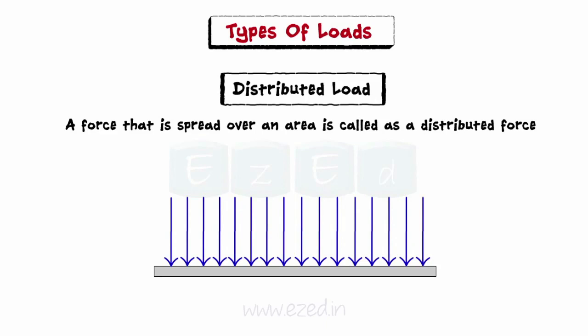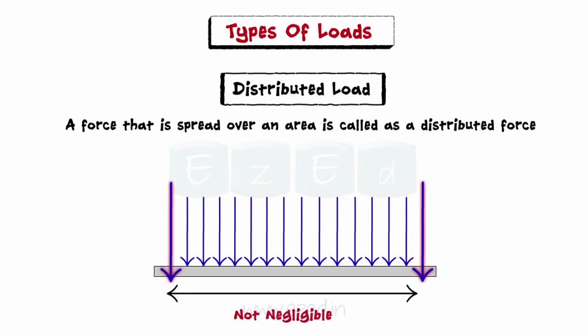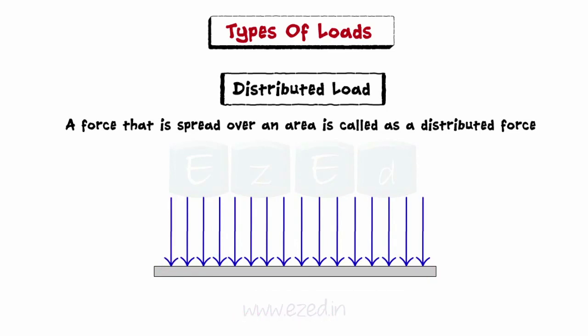When forces are applied over a region whose dimensions are not negligible compared with the dimensions of the body, we must account for the actual manner in which the force is distributed. This is done by summing up the effects of the distributed load over the entire region. For this purpose, we need to know the intensity of the load at any one location. That is, we find the resultant of the distributed forces acting at a single point.